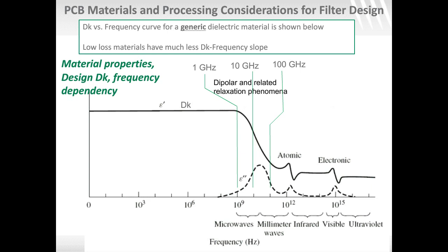Once you get up into the higher frequencies, a few megahertz up into the gigahertz range, that's when these dipolar moment relaxations start having an influence, and that actually augments the electric flux, which causes the dielectric constant to change with frequency. So normally what we see in the range of frequencies that we test, we see a decrease in dielectric constant with an increase of frequency.